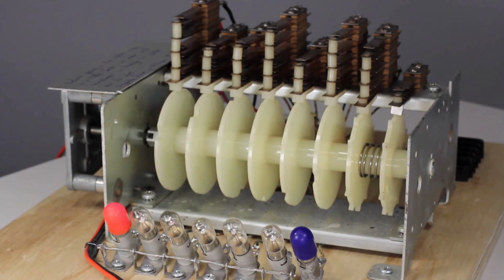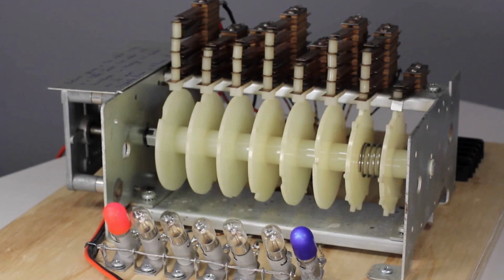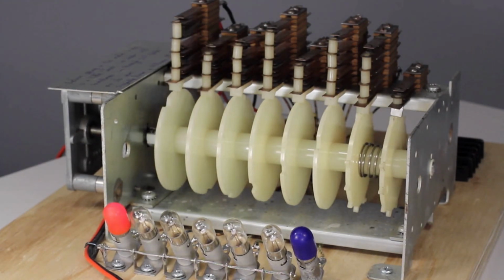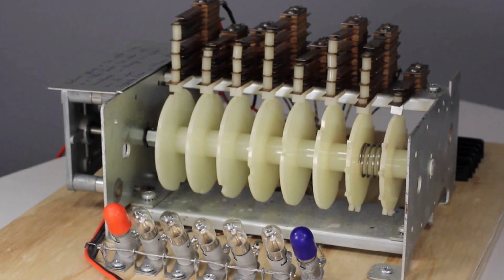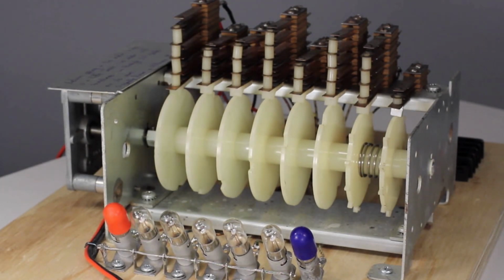And it always steps through 180 degrees to what's called the home or index position, and it stops whenever it gets to that position. But if you look at the cams on the left, they're activating their switches one at a time and just once per half rotation. The two cams on the right end are activating multiple times every time this motor runs. So that's going to be the key to how I get from one event to multiple events. I have to engage the score motor.